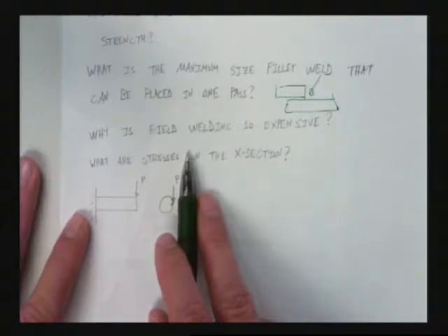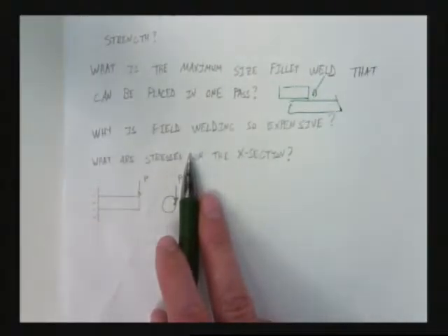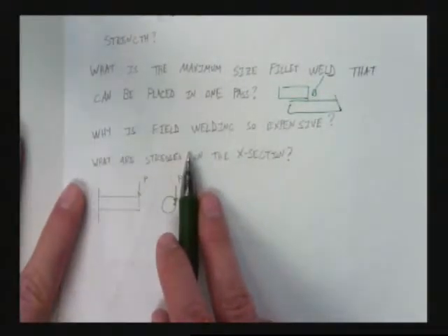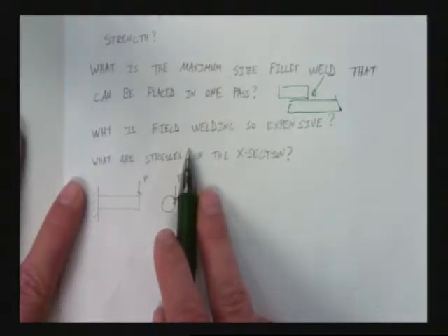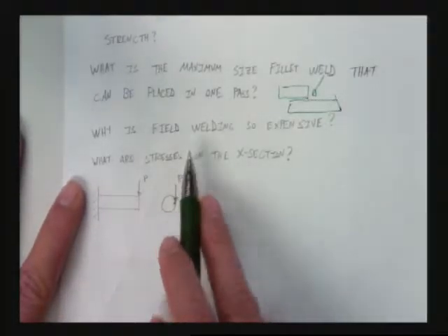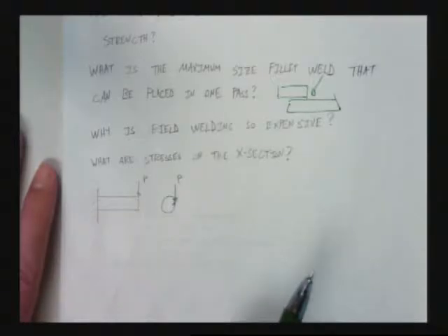Inspection services are very challenging, much more stringent. I mean, it's because we're relying on those welds to carry heavy loads. They cannot have imperfections in them, and the reason why is because imperfections cause stress concentrations. Stress concentrations cause fatigue problems. Fatigue problems mean something will fail suddenly under a load that it had seen multiple times before.